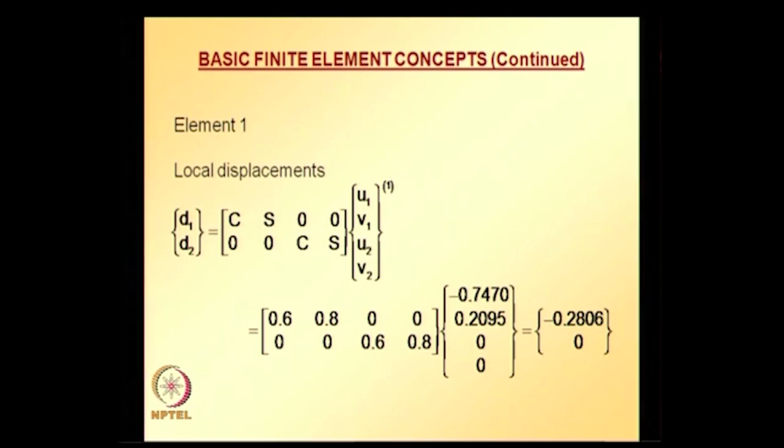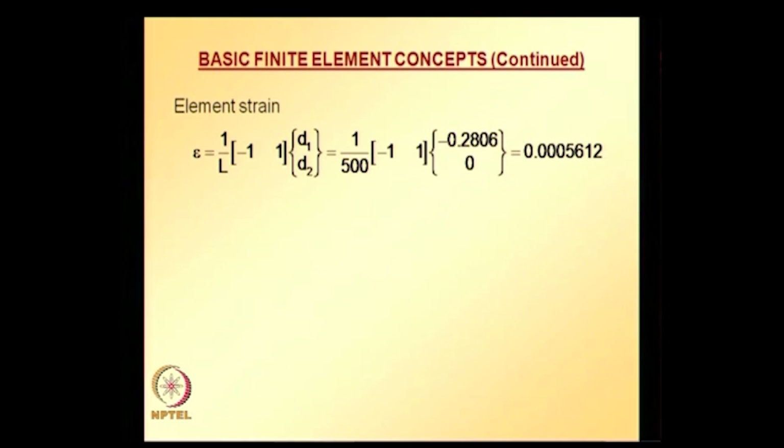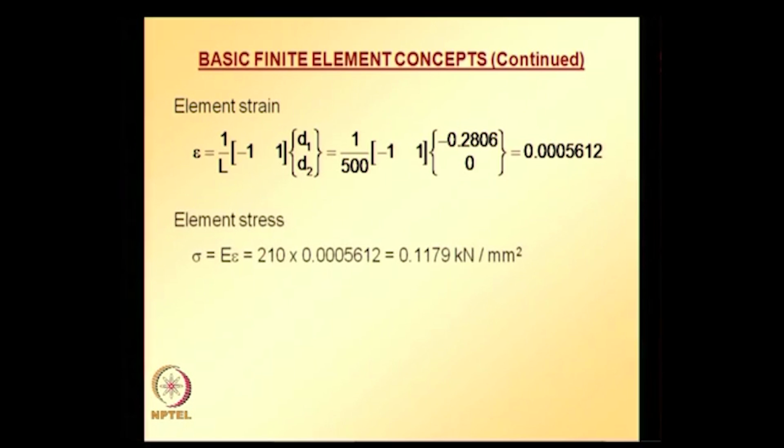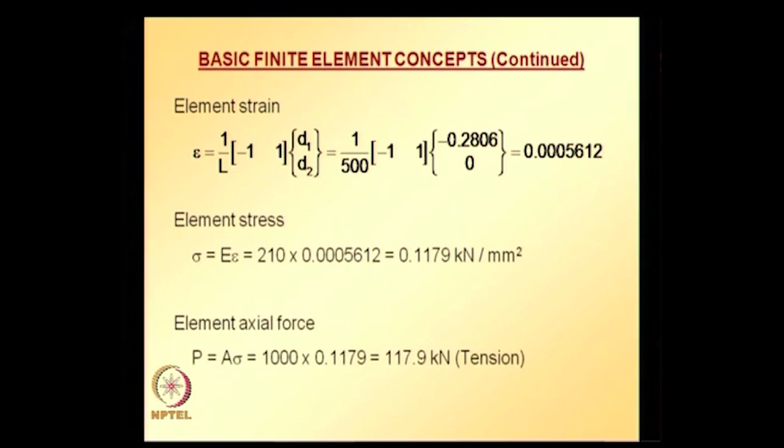we can find the local displacements, and using the local displacements we can calculate the element strain and element stress and axial force, and the axial force turns out to be positive. So, it is a tensile force. Similarly, for element 2,